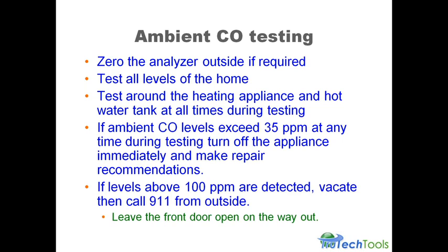We want to test around all levels of the home. We want to test around the heating appliance and the hot water tank at all times during testing. If the ambient CO levels exceed 35 parts per million any time during the testing, turn off the appliance and immediately make repair recommendations, okay? Because we're talking about, somehow you're getting CO into the space.